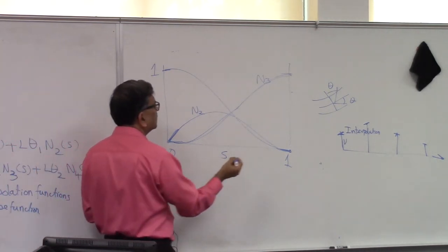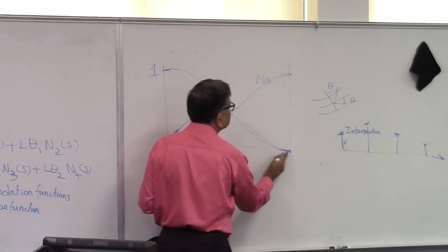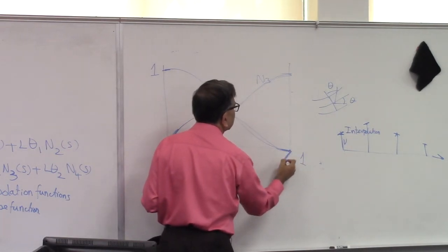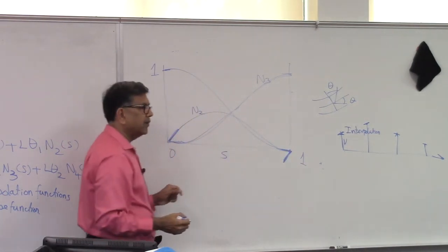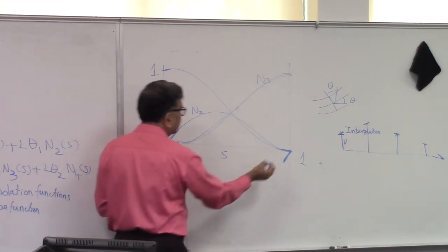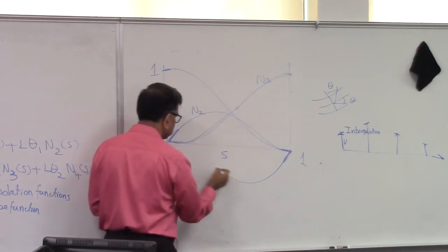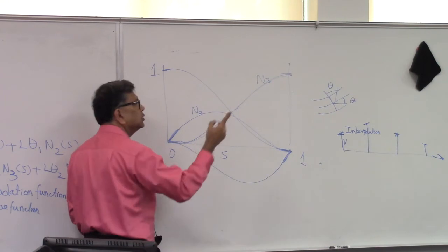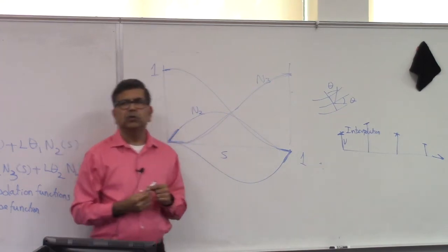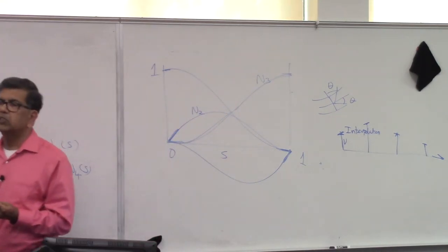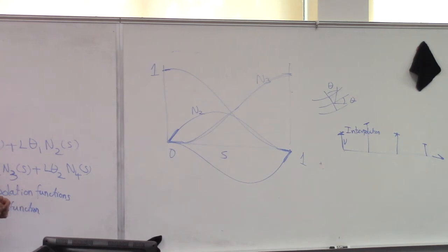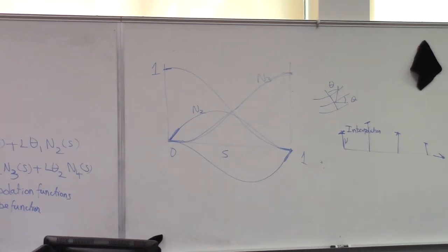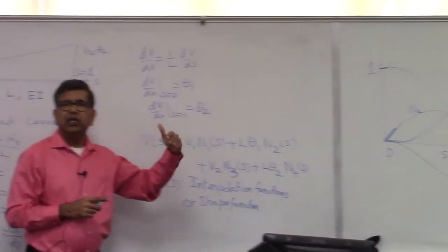N4 should have positive slope here, slope equal to 1, and all other degrees of freedom will be 0. So it has to be below. So it will come like this. So you can see N4. So these are the 4 shapes. They're called Hermite polynomials. It is given there. So we derive such shape functions for every element.